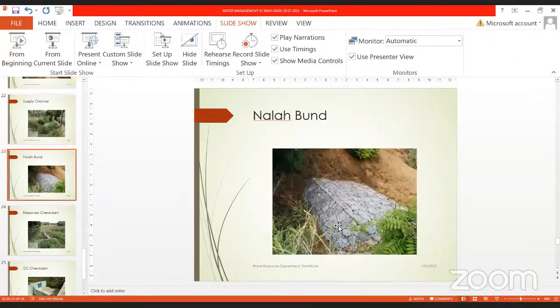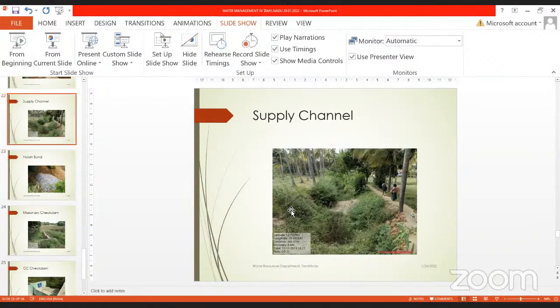This is nothing but an arrangement of several pieces of random rubble tied up with some gabion structures. This will be arranged in this form and covered in a layer of gabion, that is a steel mesh, so that the entire mass cannot move, and it's very cheap. It comes to around 8 to 10,000 rupees. That's all. These can be built across smaller drains like this.